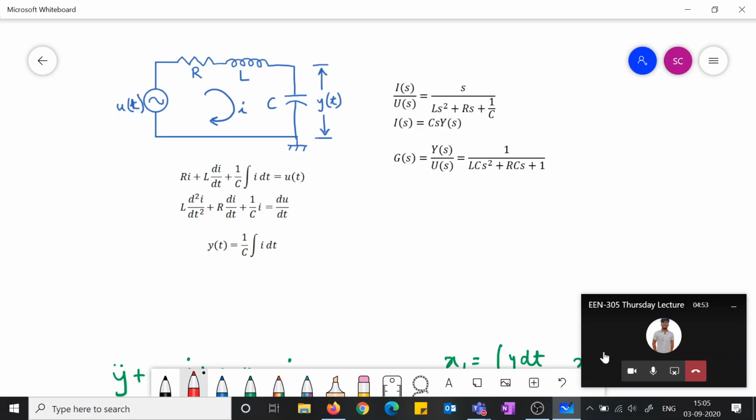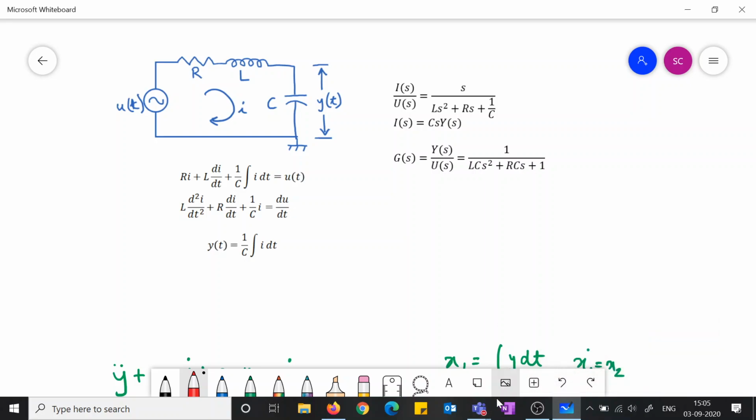So you can see that here this was the circuit, RLC circuit, where there was a mistake in finding out the transfer function actually. So if you go back to the video, you will see that the final transfer function had an s in the denominator along with this expression. So it had a pole at the origin, but it is not supposed to have it. What actually the mistake happened is this.